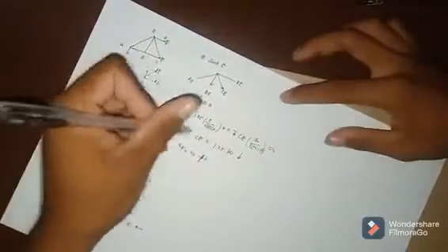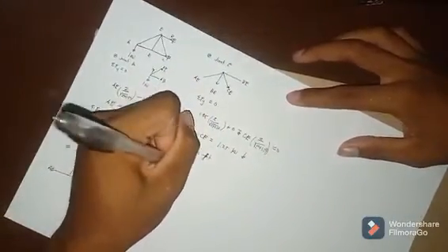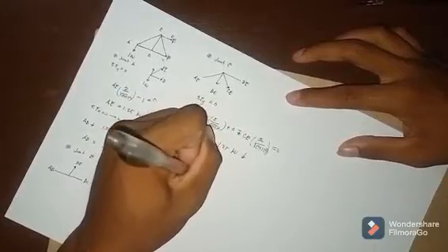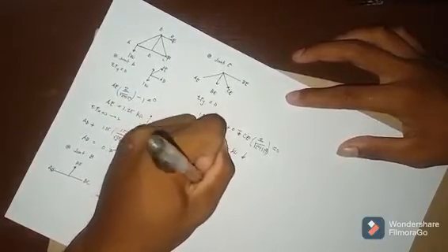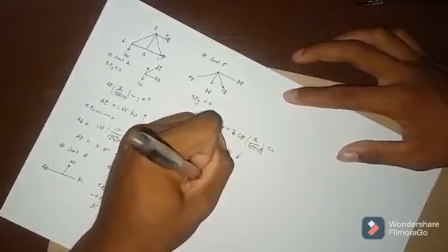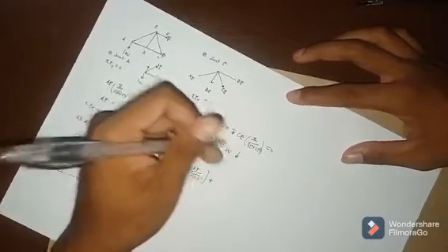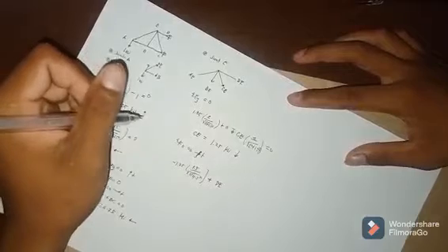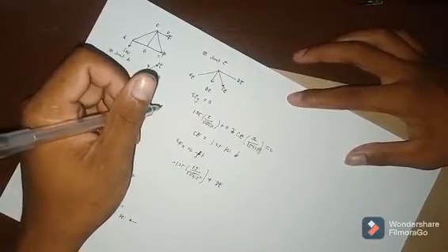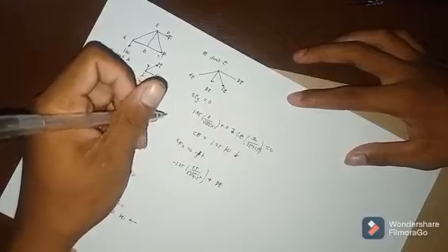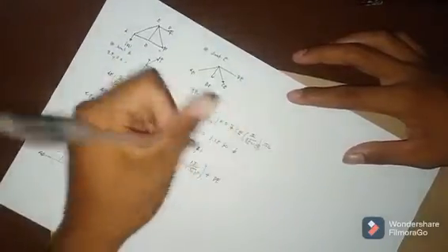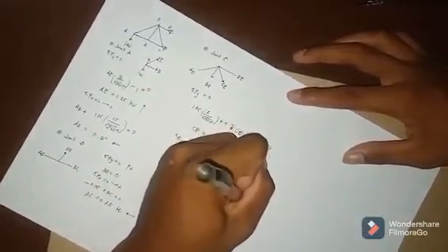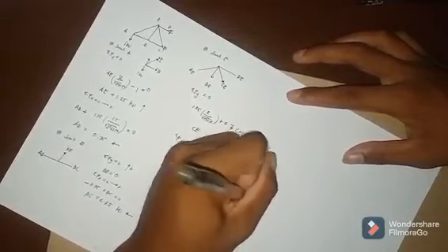So we can see our AE has horizontal, which is negative 1.25 times 1.5 over square root of 2 squared plus 1.5 squared, and plus the DE, and our CE, which is facing downwards, minus 1.25 times 1.5 over square root of 2 squared plus 1.5 squared, equals 0.